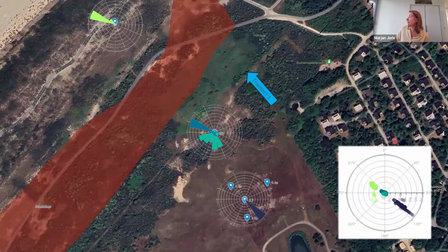If we visualize these flow measurements on this heat chart, here we combine the direction, which you can see here in degrees, with the velocity. Closer to the center is a slower flow velocity, and further away is a higher flow velocity. We can see that indeed the colors are the same. Here groundwater is flowing to the southeast, and in the central well, we can see the direction is changing. It is changing, but flow is very low.